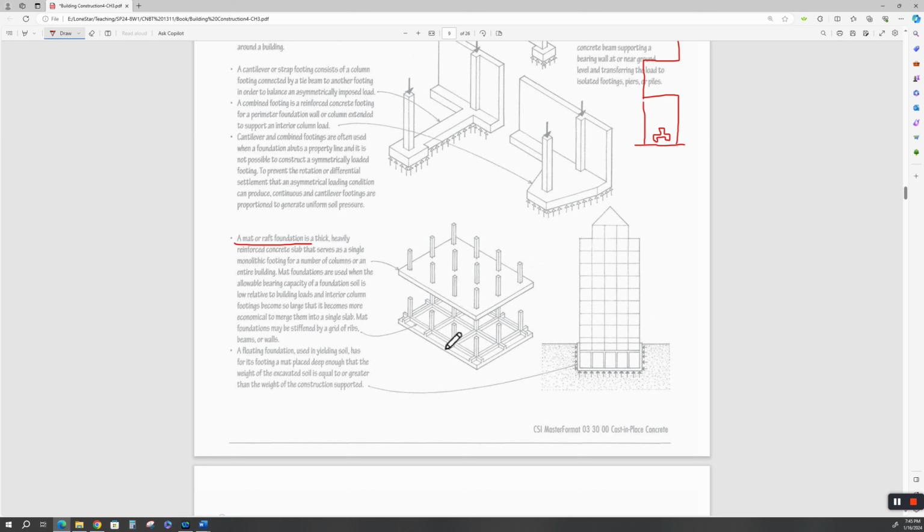Anytime that we've done anything that needed something like this, we just flipped it upside down. And these beams were underneath this, and it was a reverse mat. So we didn't call it a mat footing. We just called it a foundation footing with grade beams underneath it that corresponded to the column lines all the way across. Basically, it's like a waffle. It's upside down. And the top part of the waffle's flat.